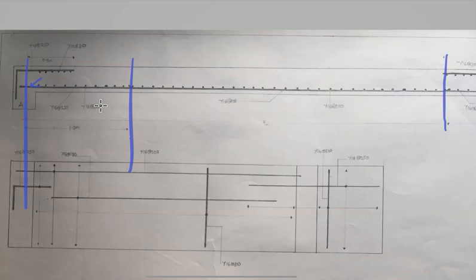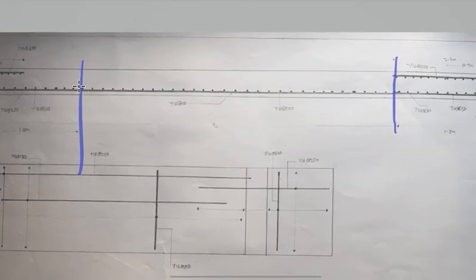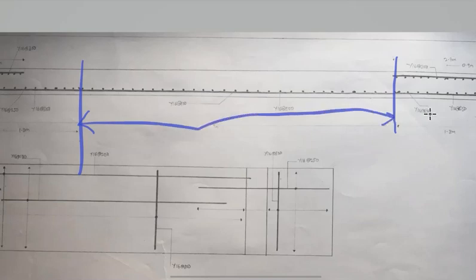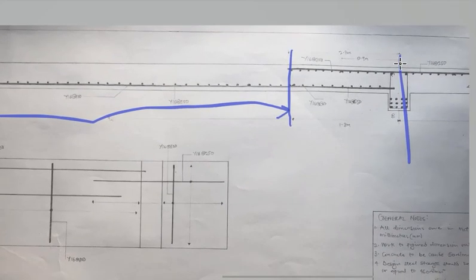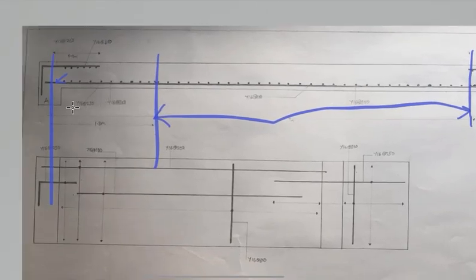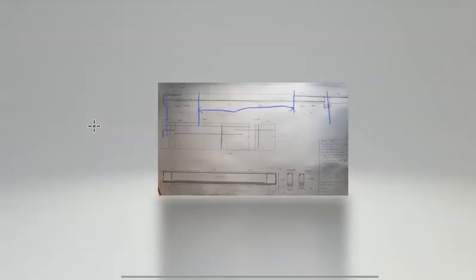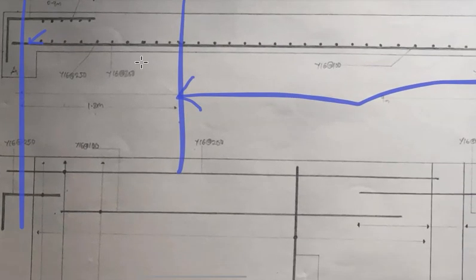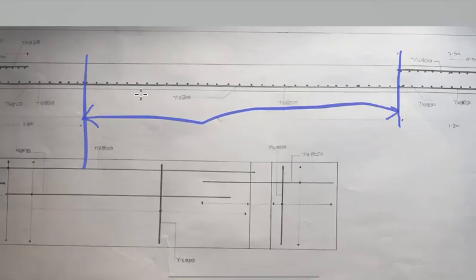effective span. So now let's go to the curtailment topic. For a simply supported slab, we curtail, meaning that we cut, because we don't need some area of steel at some strategic places on our slab or beam. The place where we most need steel is at the center of every slab or beam, where we have the maximum bending moment, which is always positive. From the support to about 0.2 of the length of the slab or beam, those parts are not very effective speaking about bending moment. So that is why we are using a lesser area of steel.